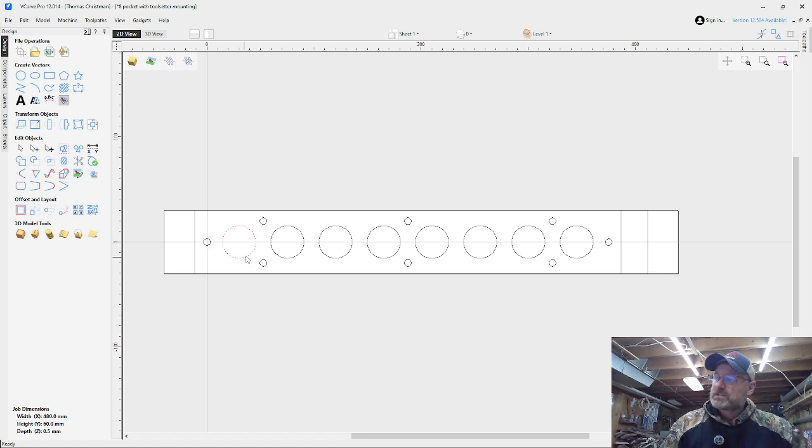And then what I did is I did an offset of all of these pockets, so that I drilled all the way through my table, so when I have longer bits, they have plenty of length to drop down through the table. And then obviously you can do the outside of this whole thing so that you can pocket out for your entire ATC so that it fits down in your pocket.